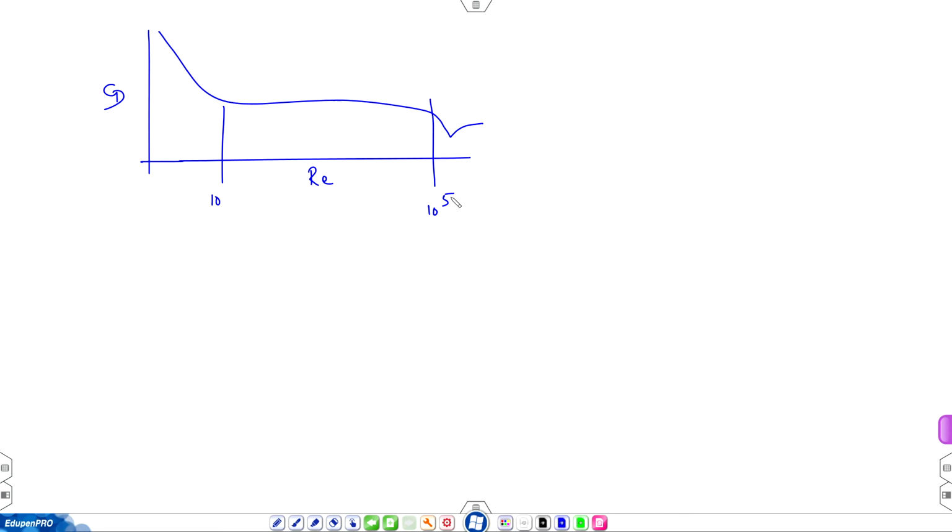There is no jump, but you can see the initial part goes down, that is Reynolds number increases, drag coefficient decreases. What happens to drag itself? Reynolds number is proportional to velocity, but drag coefficient has u square in it. So, as velocity increases, if you look at drag itself, it also increases linearly, because drag coefficient decreases as 1 over u.